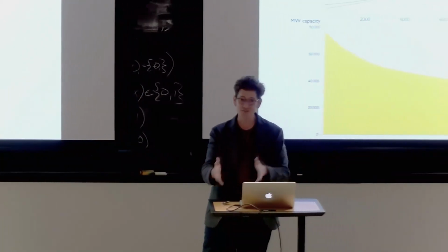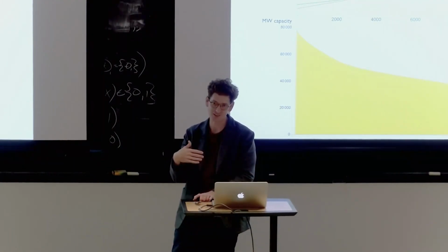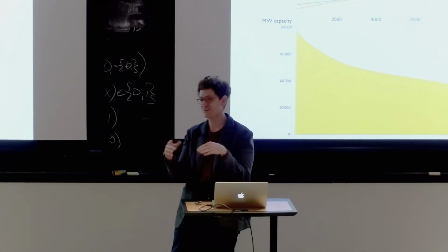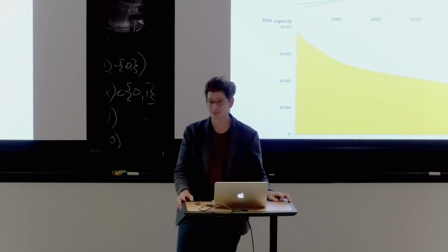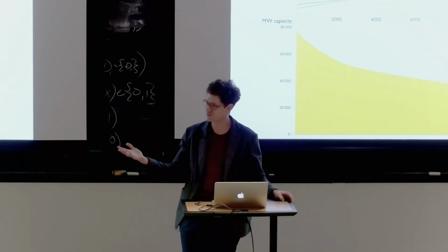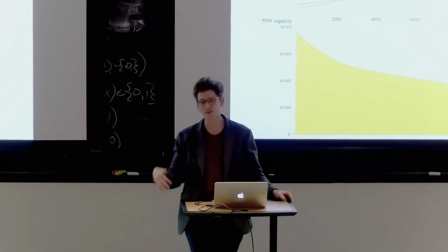But there's also benefit to having inertial generators, because sometimes you have unpredicted fluctuations in demand, and inertial generators help prevent essentially voltage drops. So, as you pointed out, there's a lot of devil in the details, and there are additional what they call ancillary services. In addition to just providing kilowatts on the power grid, you also want to stabilize the grid, you want to have high responsivity.